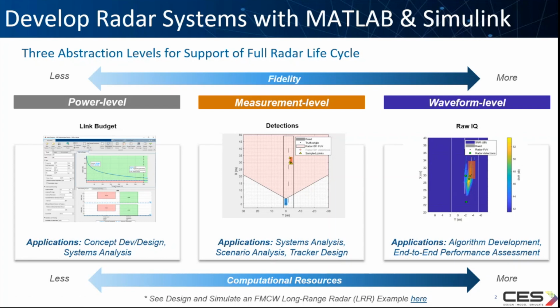If you would like to increase the fidelity of your design further, you can generate IQ signals from your radar design by modeling different components, including the RF circuits and the antenna of your radar. Modeling radar at this level will help you with designing and verifying the signal processing algorithms for radar and performing an end-to-end performance assessment of your design.